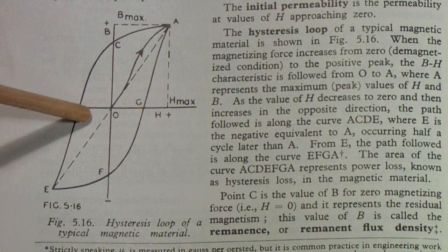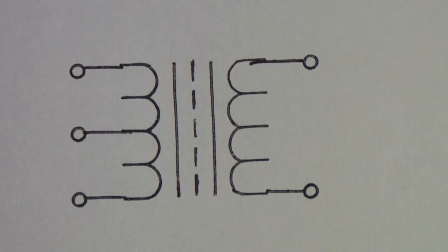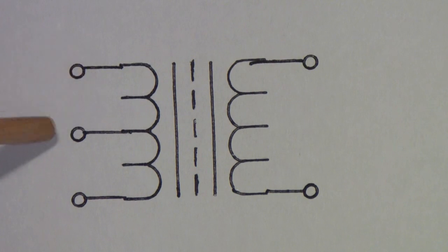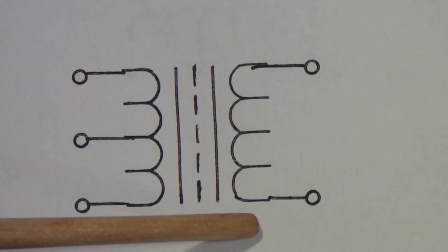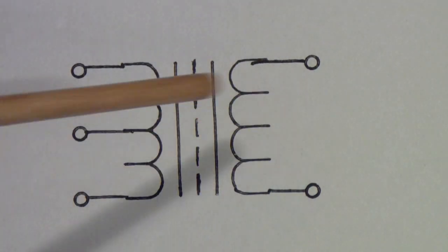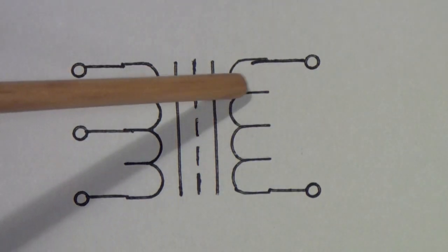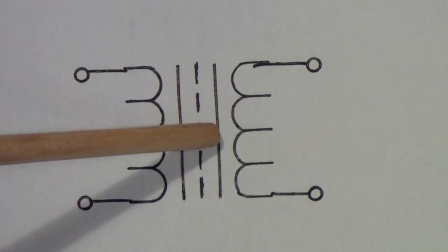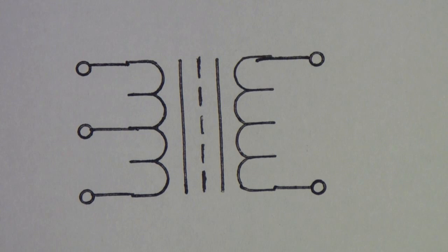Instead, we're going to talk about another problem with output transformers called leakage inductance. Think about a transformer. In this case, I'm showing a transformer which has a tapped primary and an untapped secondary, but of course you can have taps on these to adjust. For example, on this side you might have the speaker, so you might have different taps. So for example, this might be for 16 ohms, you might tap the center for 8 ohms, you might tap this for 4 ohms, and so on.